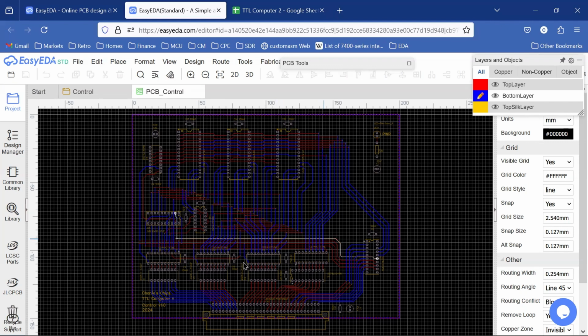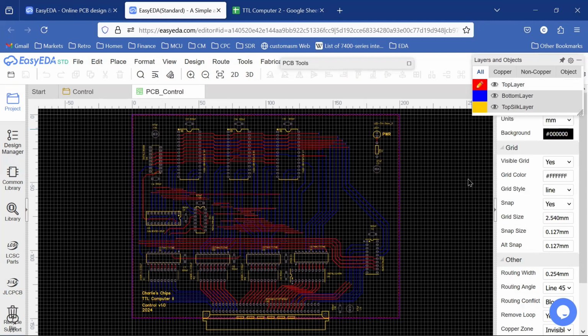Each of the chips were just pulling down straight from the bus lines, so we didn't have to worry about any crossovers. And then once the wiring was all done, I just chopped off what was not needed on these bus lines. So these red horizontal lines are what's left of our bus lines after they were shortened up. And then these little series of bus lines here are for all of our clock and clear signals, input signals to the card.